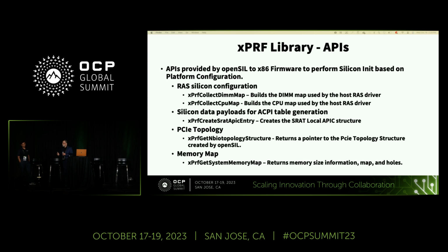XPRF stands for Platform Reference Firmware. So these are the things that the library exposes. It allows you to collect the DIMM map, and builds the ACPI tables, or at least the data that the host firmware can take and build the final ACPI tables to be pushed up north to the OS.